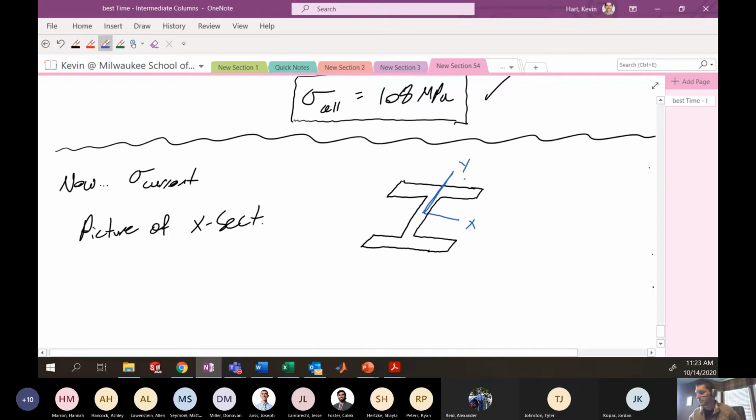All right, so I know I have an eccentric load on this cross section, located about here based on the picture, and it's pushing down with some value P. I know it's located off the center of the cross section by this length here, which is the length E. I think it's given in the problem as 0.125 meters.